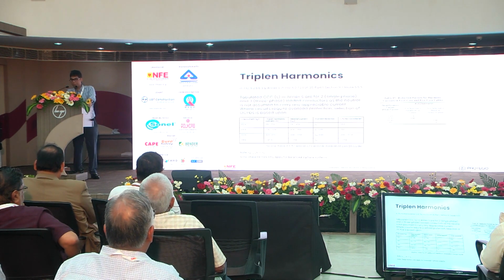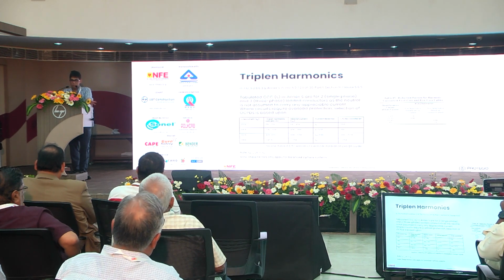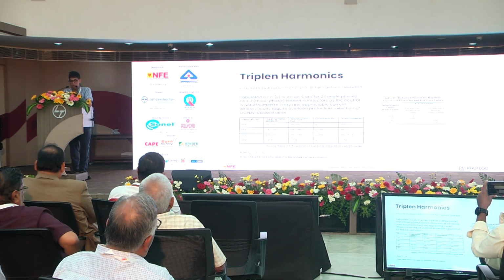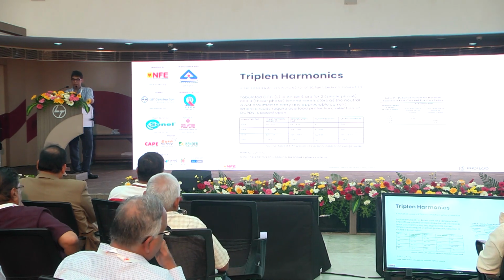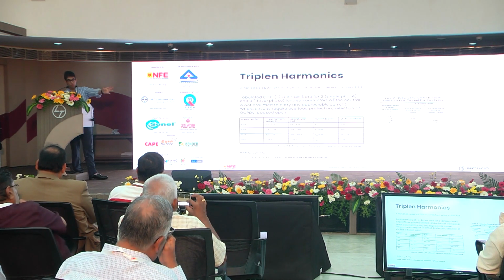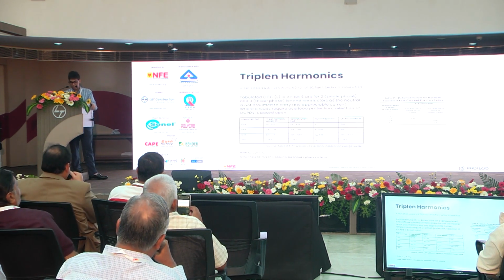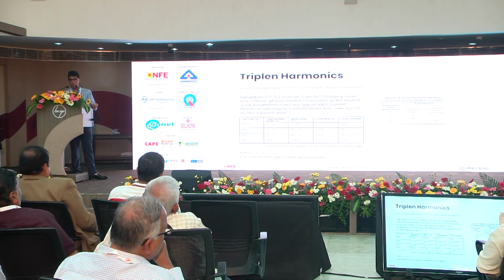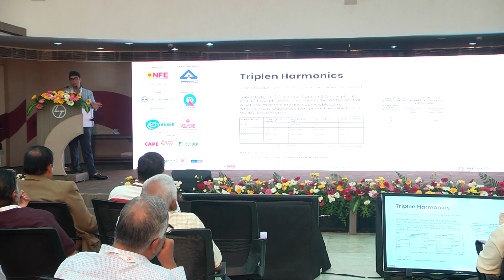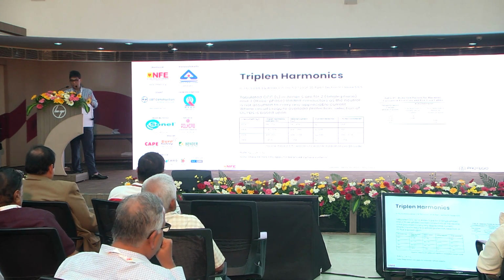Usually equipment manufacturers will give you a THD percentage for their loads. So depending on the load, you will get a THD percentage. Now, because it's triplen harmonics, we just need to multiply it by 3. So if it's 0 to 15%, then on a 100 amp load, all we need to do is 3 times 15% times IB, which is 45 amperes. So that is going to be the neutral current.